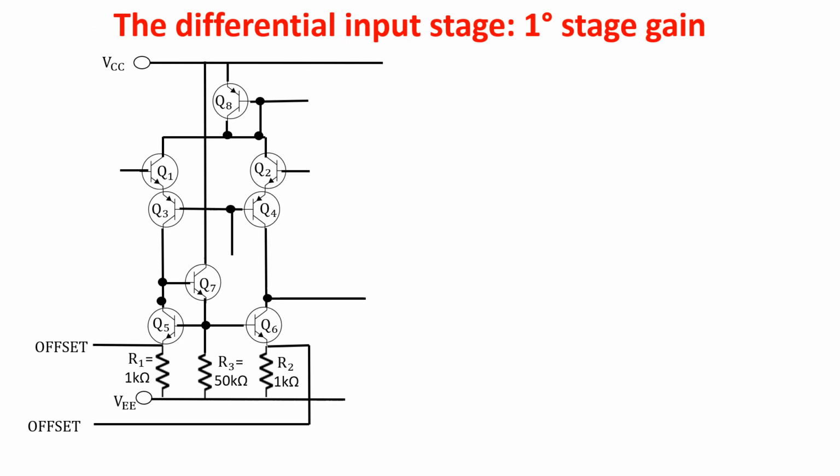Let's see the general working of this input stage, which presents as input a differential pair consisting of an emitter follower and a common base to provide voltage gain. Let's say we apply the differential voltage in this way, thus creating an AC virtual ground on the bases of Q3 and Q4. In this case, the degenerating resistance is equal to the resistance of the emitter, 1 over Gm.